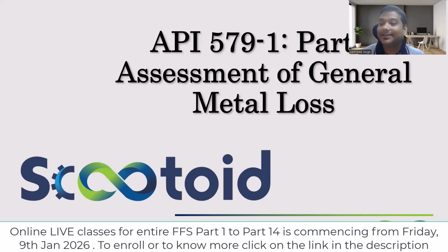All of us understand that corrosion allowance with which you have started, that is just an estimation based on experience, based on similar service conditions. It's not an exact value, isn't it? Corrosion allowance with which we start the design, it's not a fixed value. It's just an estimation which we have taken. Now it has to be assessed after every inspection. So I've done the inspection after 5 years, so I'm expecting 19.25 as the minimum thickness which I'm having. Now what if you got the thickness as 19.1?